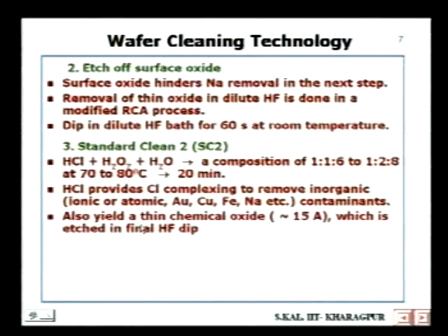This step also yields a thin chemical oxide of the order of 15 angstrom thickness, and this chemical oxide is also removed by a dilute hydrofluoric acid dip.